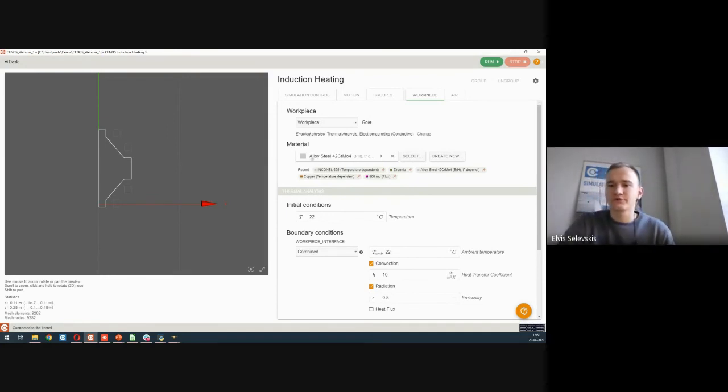How do you count anisotropic skin depth effect? That's actually a good question. I have not really tried that, but I would think it's how the anisotropy happens in CENOS. So if you want to have laminations, you would have the geometry as a single block, and then with that expression which I showed in the documentation page, you would set it up as if it was lamination.